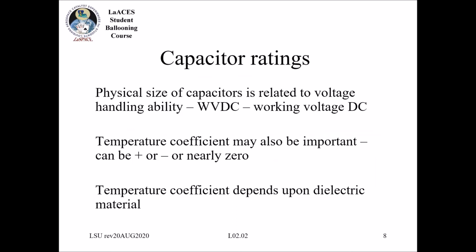But important point to this is not only are some of them polarized, but all of them have a working voltage. So whenever you are looking at what capacitor should I use, oh, this is requiring just a 1 microfarad capacitor, you need to go to that data sheet and actually make sure that that capacitor is rated for that voltage. And ideally, I like to have at least 2 times the voltage of whatever your maximum voltage you're going to be working with on a board. So if you're working with something that's a 12-volt system, you can find capacitors that are rated for 25 volts and so forth.